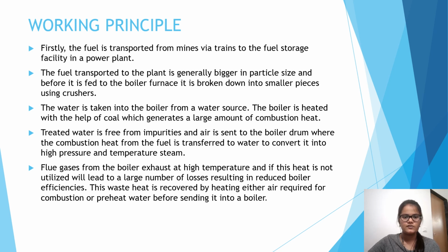Flue gases from the boiler exhaust at high temperature, and if this heat is not utilized, it will lead to a large number of losses resulting in reduced boiler efficiencies. This waste heat is recovered by heating either air required for combustion or preheating the water before sending it into the boiler.